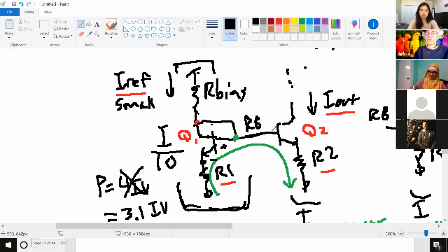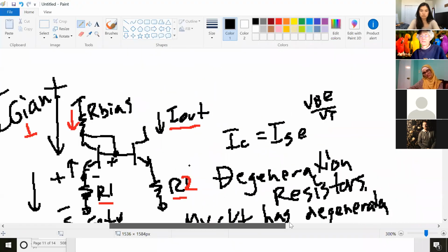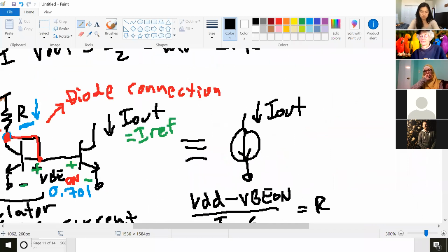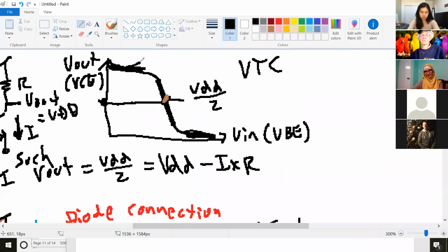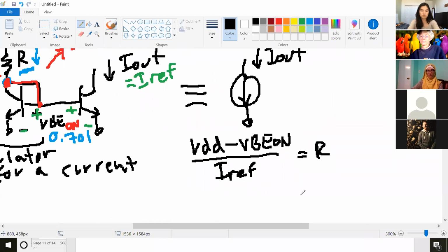But if this voltage right here changes, then you won't have that current through your amplifier, and your V out will be sitting, going back up here, wherever it is. Maybe way up here? Yeah. If you don't have the correct current going through your amplifier, you could be sitting up here or down here. So you want to keep that voltage on the base of your transistor.